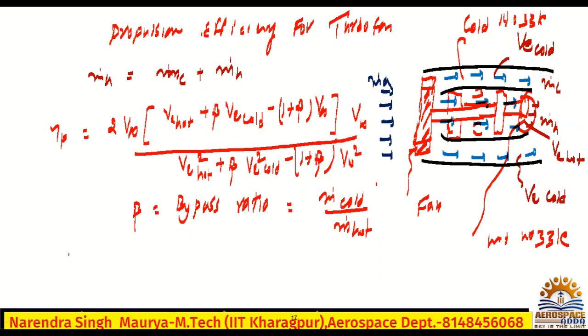So the compressor pressure ratio you are increasing here. Another thing you can say, the effect on the velocity in cold air, again it is not going to change because of the compressor. Whatever the cold air velocity, that will be constant. It is not going to change. Only the effect you are going to get is in the hot, because we are changing the compressor pressure ratio.